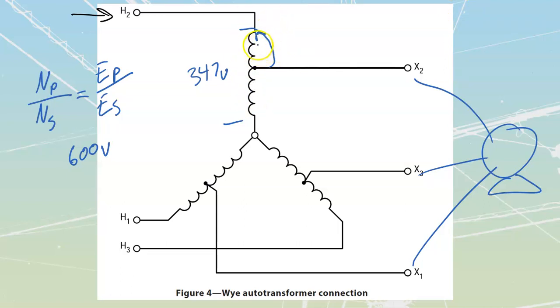But as I move down from the top point over here, I'm going to be dropping the amount of voltage on the outside on this motor load. So what I can do is have a sliding set of taps that I start all the way down over here, on all three lines. That means that when I initially close in on my motor, because I'm only seeing a small amount of voltage, I get a small amount of inrush.